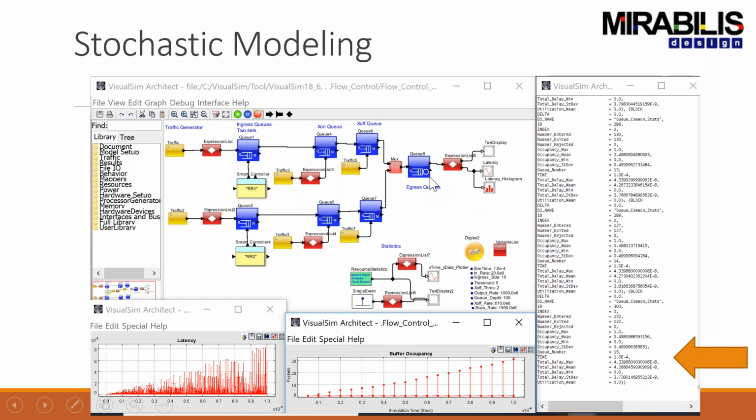Now, one of the things that's critical is that, remember we talked about where I need to know what the credit available here is, and I need to lock out credit before I can start the transmission. What we've done here is, rather than having wires go back and forth and be able to measure the information and feed that back in, we have created these registers where this information is already stored.